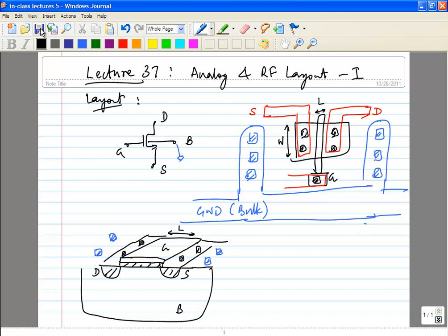So typically the way it works is, before the layout engineer starts working on it, first of all the designer needs to design the circuit such that it can be laid out directly. Okay, preferably giving some information on the signal flow, because the layout engineer will typically not know a lot about the design of the circuit itself. He won't know which lines are critical. So what you will have to do as a designer is, let's say, do what is called a floor plan.